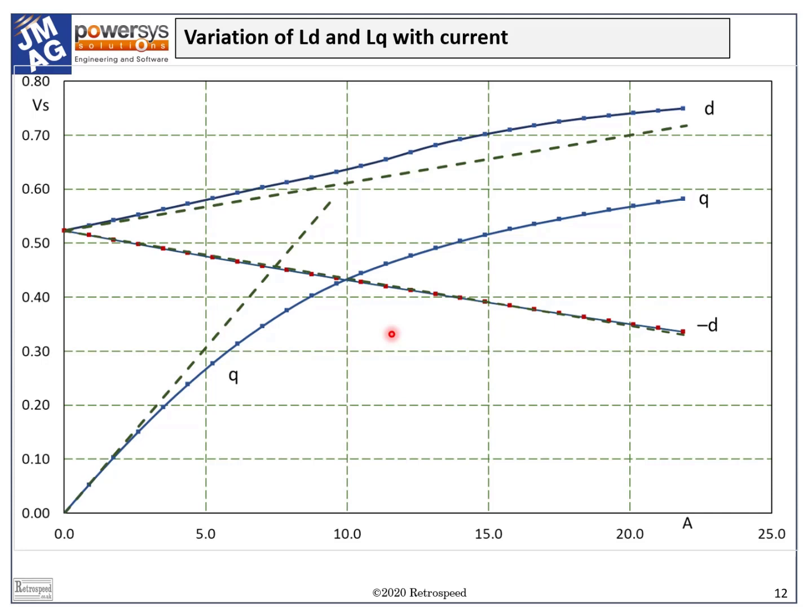Once we know the flux linkages and the current in the DQ axes, we can immediately calculate the torque and the terminal voltage. An estimate of the torque is obviously needed in the field-oriented control scheme. If we have a PWM current-regulated inverter, we will be controlling the current.